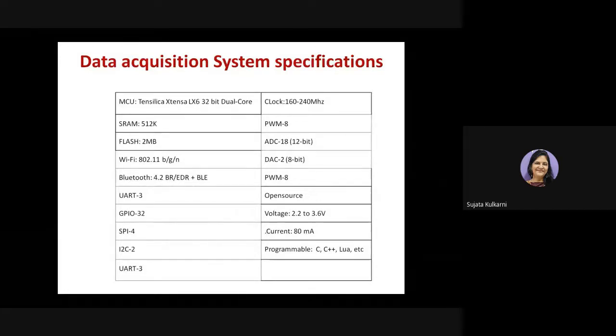And reasonably good memory, like static RAM, which is very rare, having a few kilobytes, but still we are able to get up to 512 kilobytes. And the flash, where our program memory, the entire operating system and mini scheduler, is stored, is up to 2 MB we can target. So this is, in short, the identification of a computational unit in order to implement your logic analyzer, CRO, function generator, data logger, wireless communication, and so on.